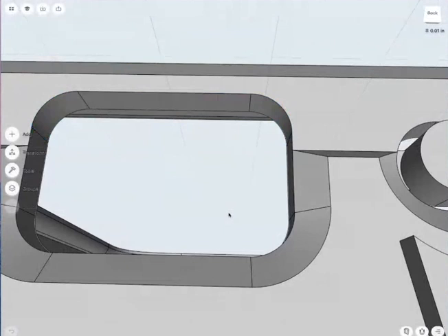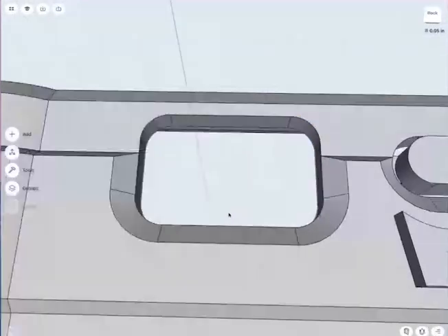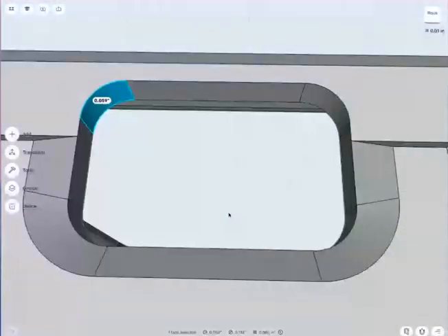Now, some people might think that direct modeling only allows you to manipulate some of the geometry or the faces. I would actually sometimes call direct modeling more interactive. Because while I have transform tools to move faces around in Shaper, I can select, for example, the surface that is part of an arc, as you can see there, and it reads out the value of the fillet. So I could adjust the radius for that fillet.